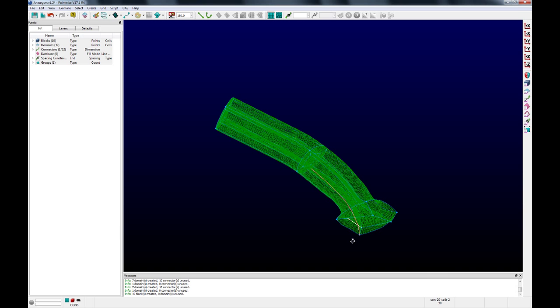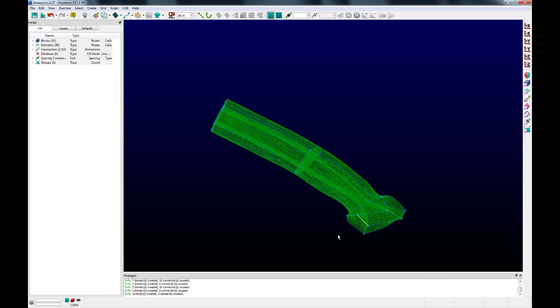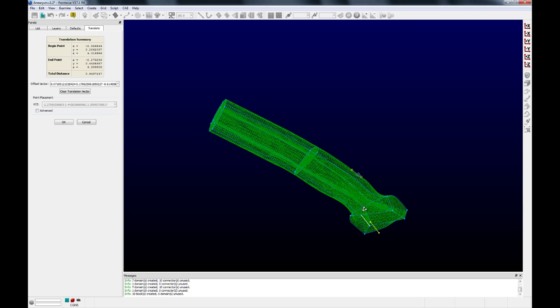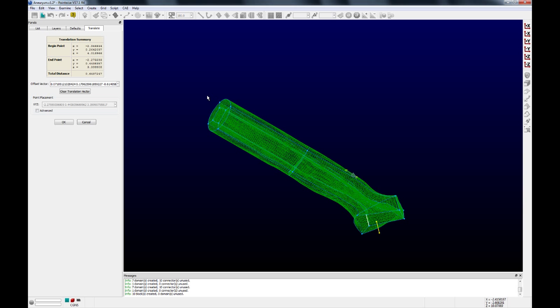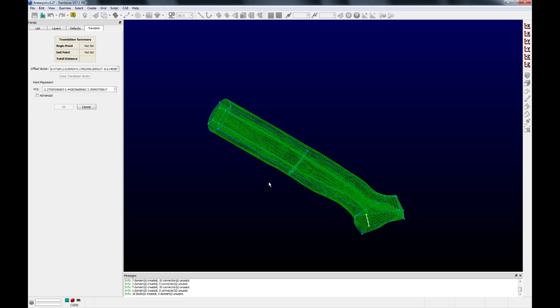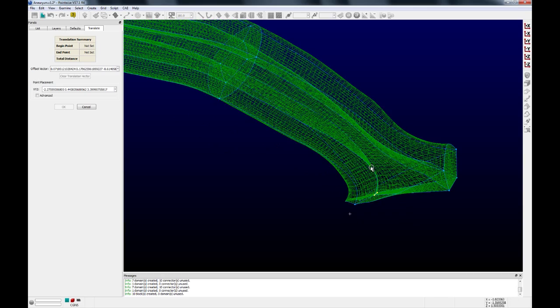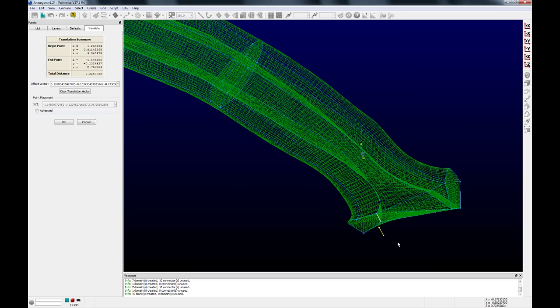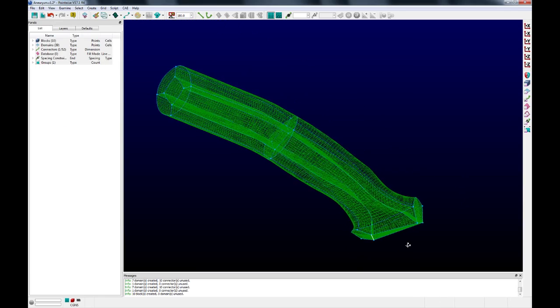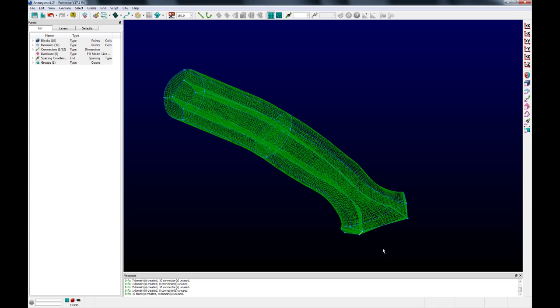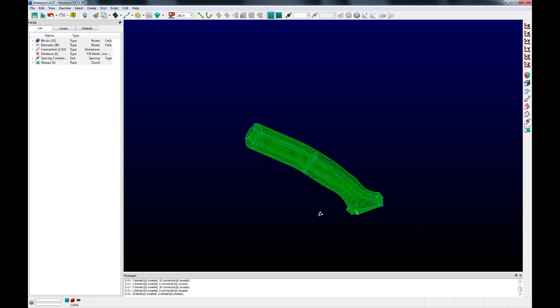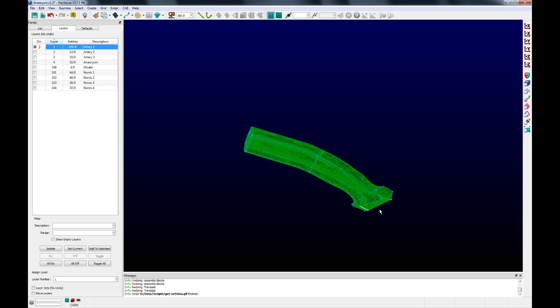And again, this is a lot like drawing the curves on the surface initially. It needs to be in the right general vicinity, but it does not need to be in exactly the final location, because we're going to be using solvers later that will smooth things over a little bit. So we're going to apply another transformation to this other connector down here in much the same way. We'll just try to give it a little bit of three-dimensionality so that whenever we go to connect it up with the adjacent topology, it matches well. So that's going to be the procedure that you would go through if you want to manually construct the mesh using an existing script, but primarily building this by hand.